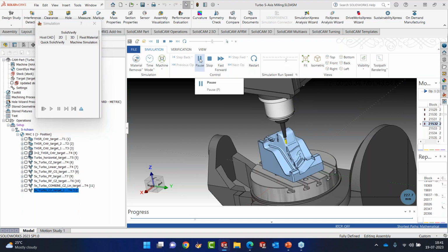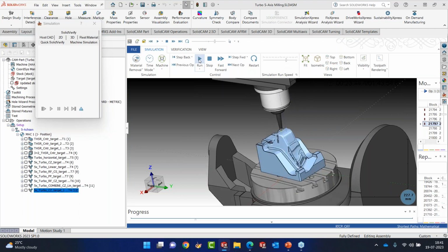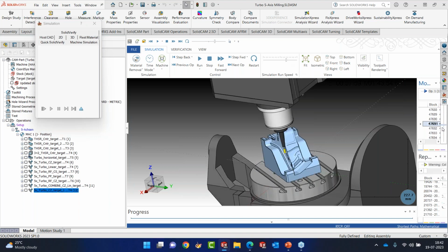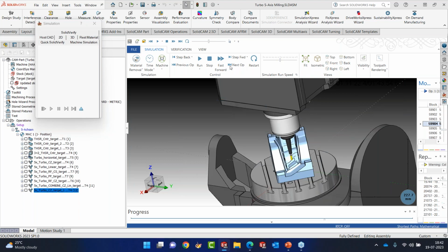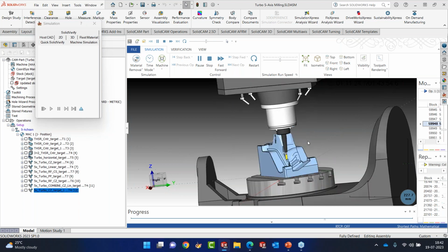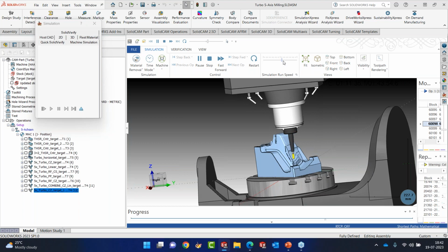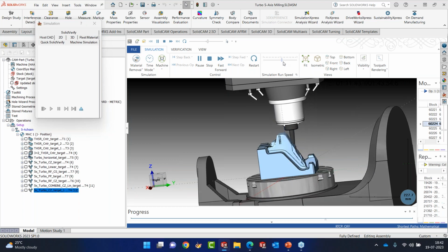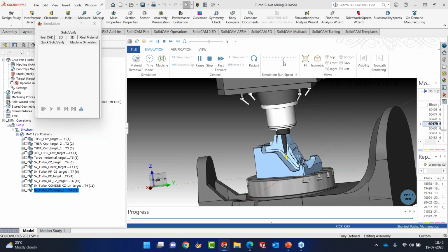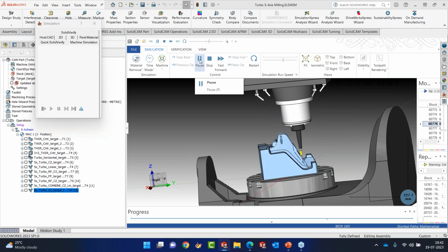Okay, now this particular tool path was generated in 5 axis itself. It was not that we generated 3 axis, then we applied some kind of collision control to tilt it. No, it's just done in the entire process. In one go, it generated a full 5 axis tool path to be used for machining this kind of a mold. For example, let's go down. You can run the tool path here. And you can see that it's doing in full 5. Wherever possible, 3 axis. Where it's not possible, full 5. Those collisions that you saw now are basically one of those 27 collisions that were unavoidable just because I'd switched off certain elements of the tool to be checked.